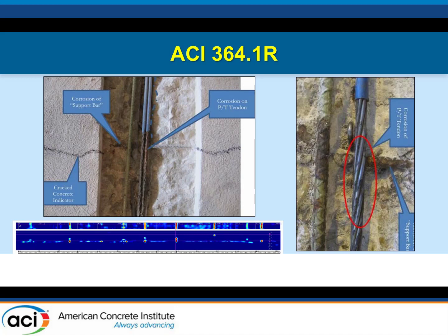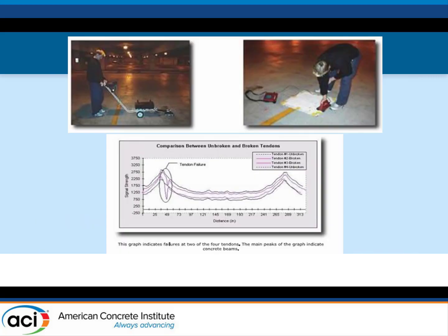These were regions where the cracks tended to align with very low cover over the reinforcing steel. So you see in this case we cut it open. You see the epoxy-coated bar on the left-hand side and the pair of tendons on the right-hand side. But it's only when you get up close to it that you can see not only are you losing the protective coating on the mild reinforcing, but you're getting pitting on the post-tensioning tendons. Of course, now what does that mean?